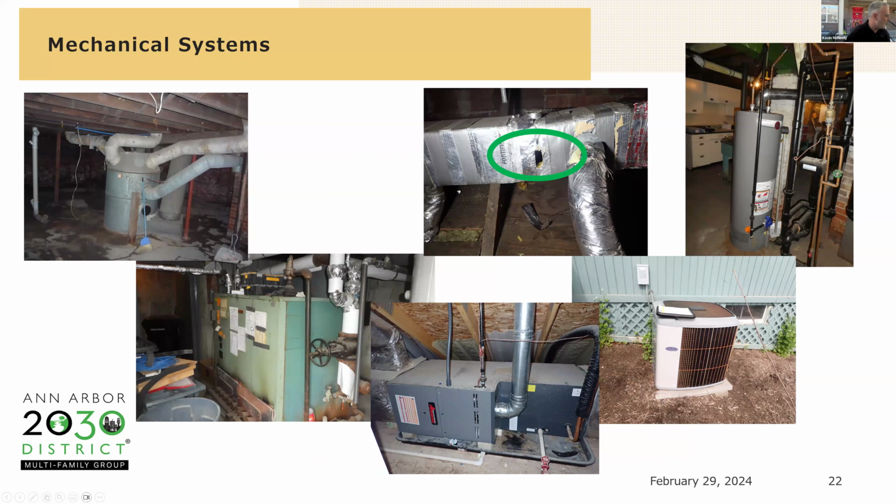But just kind of do your research. And then the other thing I can say is have all of your equipment properly sized. So have someone do the calculations. I did an energy audit on a house in Detroit. They needed their boiler replaced. The company wanted to do a BTU for BTU replacement, and that was going to be a $45,000 replacement. After I did the load calculations, it came in that the boiler could be half as big, and it saved them $20,000, a little over $20,000.